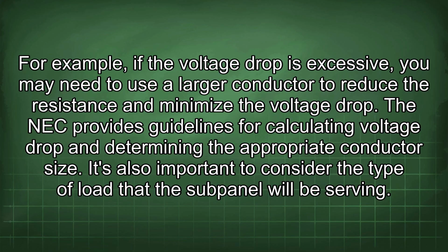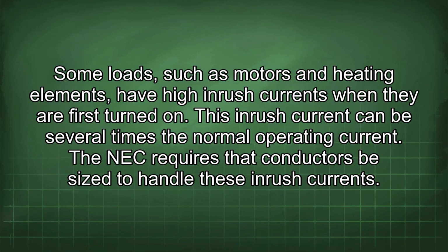It's also important to consider the type of load that the subpanel will be serving. Some loads, such as motors and heating elements, have high inrush currents when they are first turned on. This inrush current can be several times the normal operating current. The NEC requires that conductors be sized to handle these inrush currents.